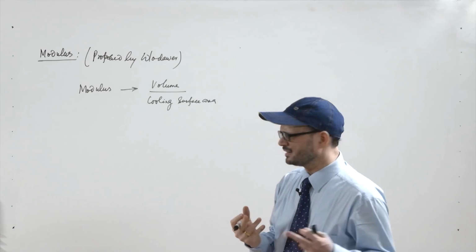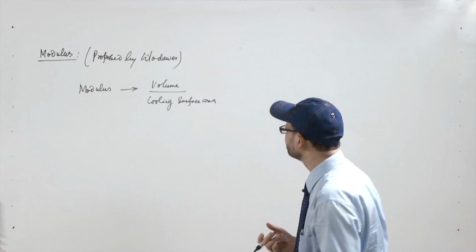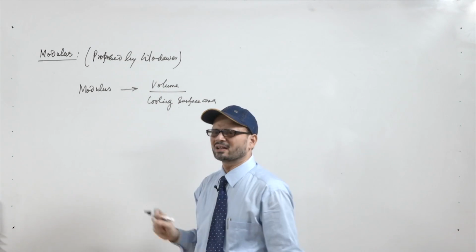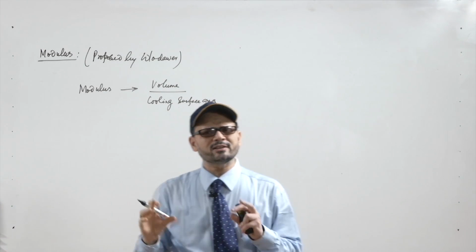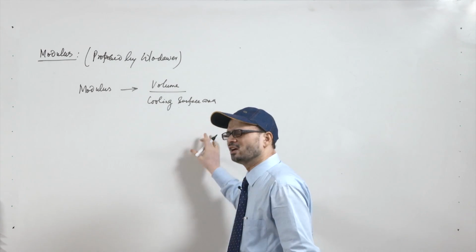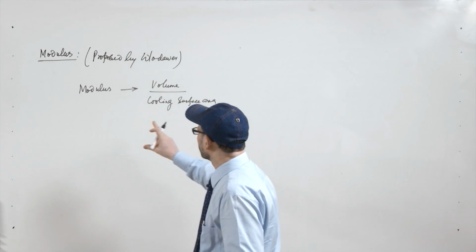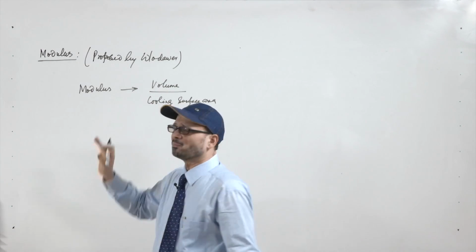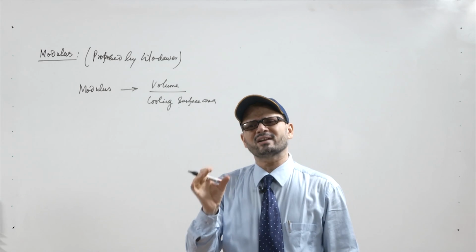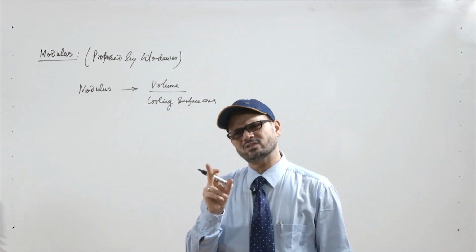What this method has suggested is that if the modulus of casting and modulus of riser is calculated, certainly for the casting to have no shrinkage defects, the modulus of casting must be less than the modulus of the riser, or in other words, the modulus of the riser must be more than the modulus of the casting.